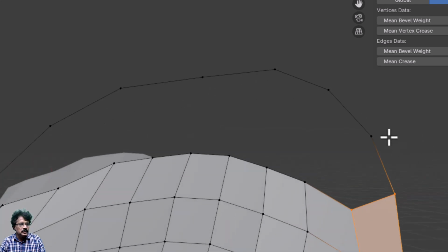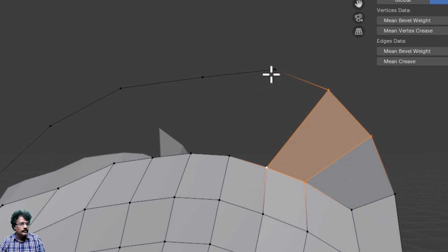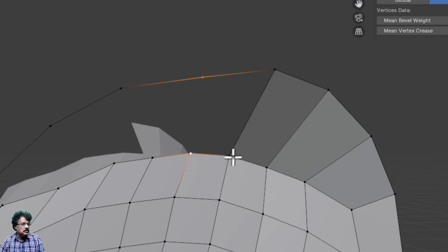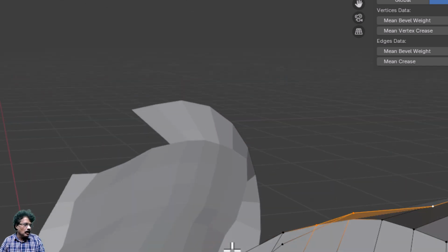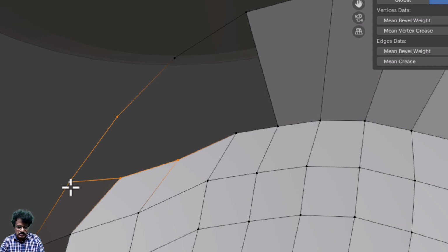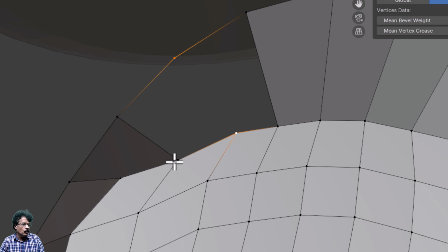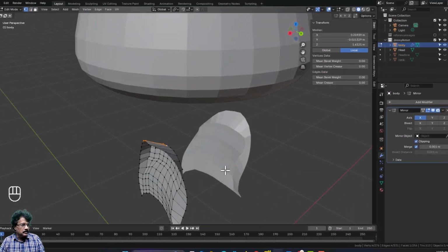and then I have this final part. For this final part I will select these faces like this, press F, then select these 4 here and press F, then these 4 here and press F, these 4 here and press F, select this with Shift pressed, these 4, and press F. Similarly I have these 4 and press F, then select these 4 and press F, and since we have chosen an even number of vertices, I get all these 4, and now I have this face ready.